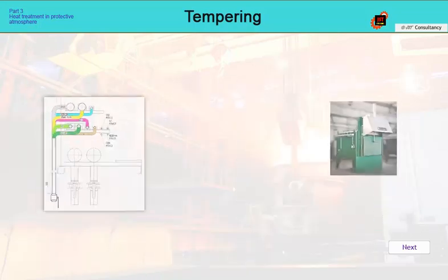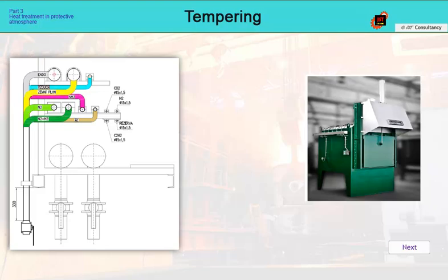If the heat treatment plant is also equipped with multi-purpose furnaces, then it usually also has a source of endo-atmosphere. It is used primarily for quenching, but it can also be used for tempering. The only condition is a safety burner inside the tempering furnace, ensuring that the atmosphere burns out in the event of its contact with air. Its composition provides primarily protection against decarburization, and at the same time partial protection against oxidation. However, there are also operational reasons for its use.